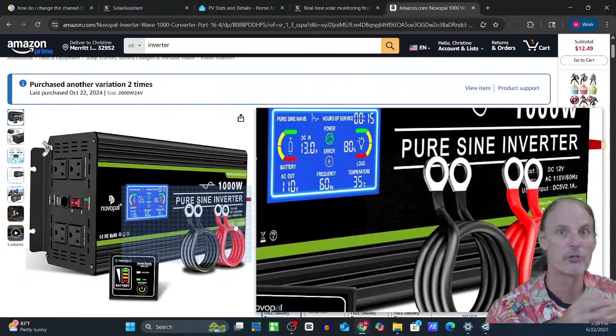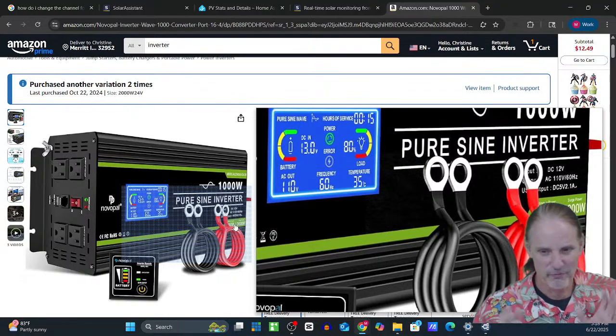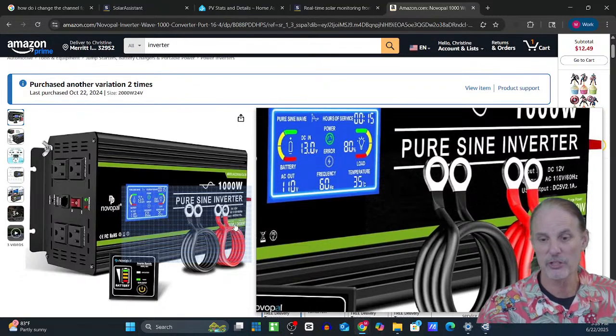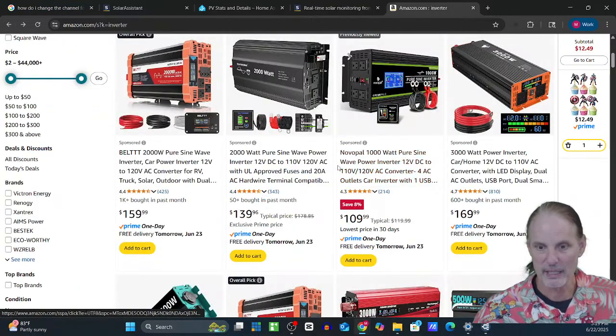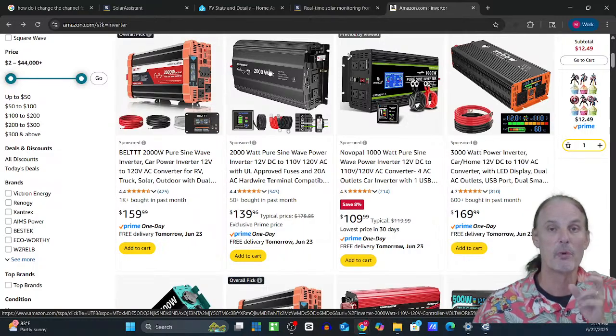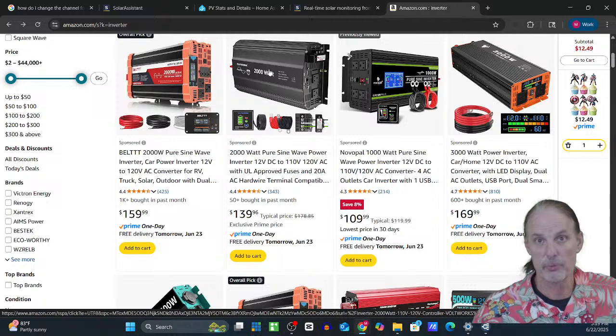There are some inverters from some companies, especially in the solar industry, that are much more legitimate in their advertising. But for the most part, all the numbers you see for things like this are garbage. They don't mean anything. Trust the normal operating wattage more than anything, and even with that, leave yourself a 15, 20, 30% buffer.